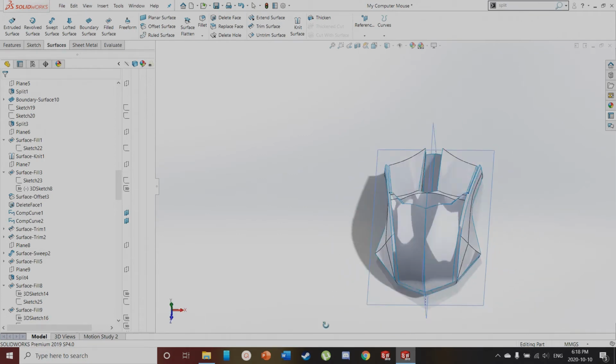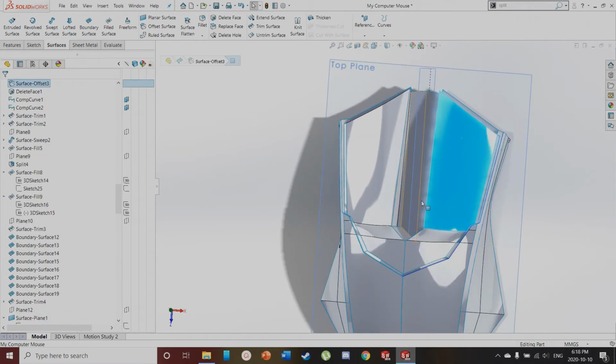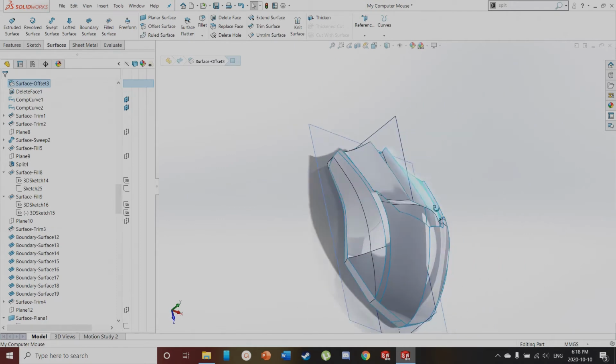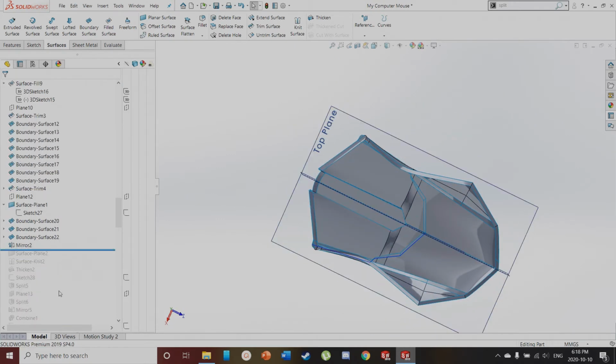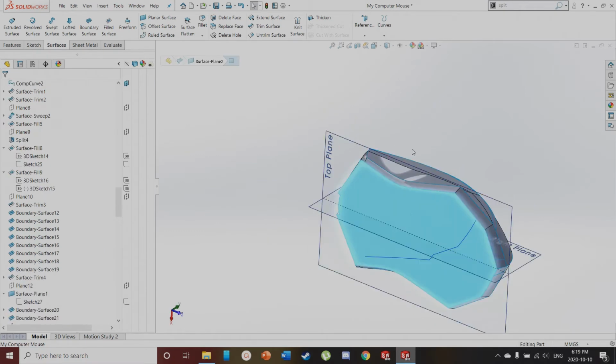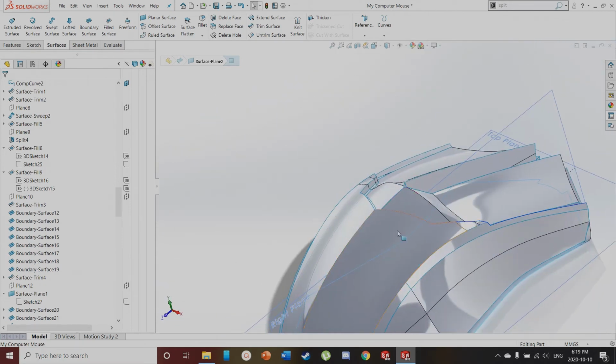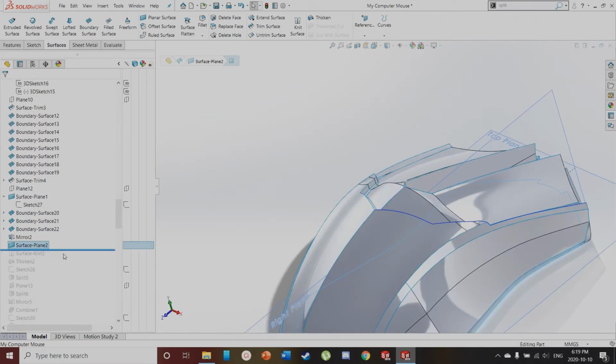You can look at it from this way, left mouse button, right mouse button. This is the slot that the scroll wheel and DPI keys will go into. Nothing on the bottom yet, but that is about to happen. Surface plane 2, bang, there it is. So now this is a set of surfaces that enclose a volume, and I can turn that volume into a solid with the knit feature.